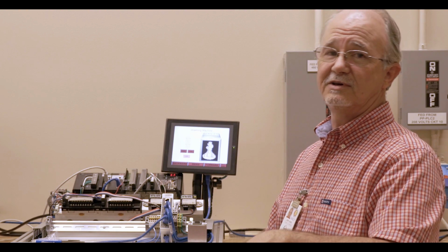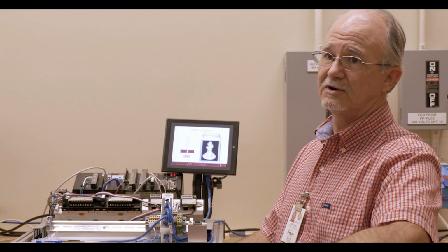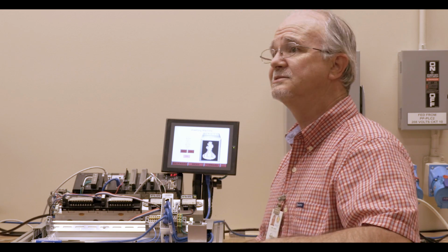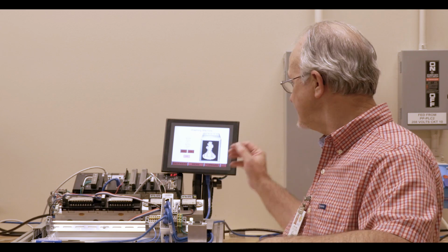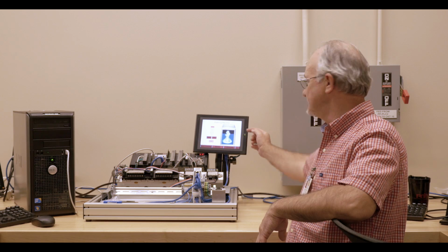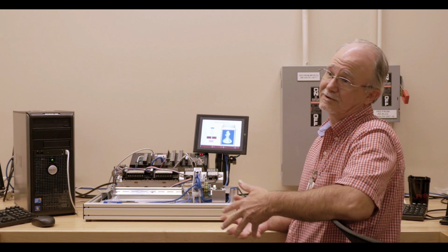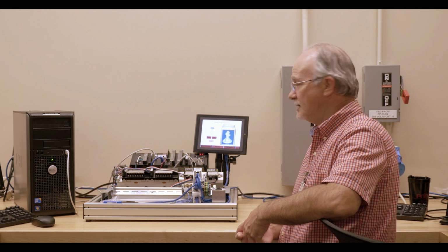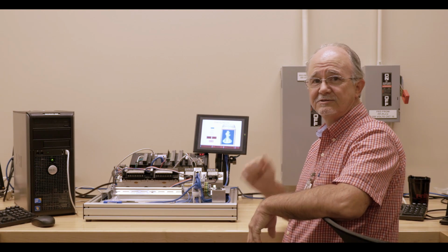Last thing we have is our little infamous washing machine. We use a multiplex instruction in addition to the timers and a couple of counters. And we'll make some pretty lights move, and we fill the liquid level of the tank. It gets 10 seconds to fill the tank. We have a numerical value here from 0 to 100. You fill up the tank in 10 seconds. 10 times 10, that'd work. We agitate the tank for 15 seconds. While we're agitating the tank, all the indicator lights across the top flash.